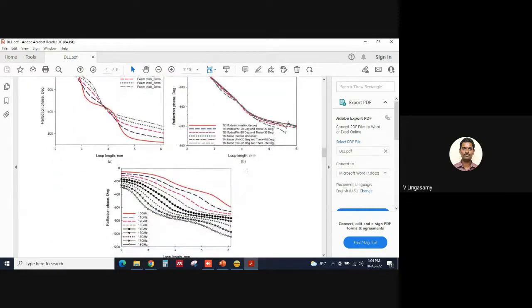This one, the unwrapped phase. These phase curves, right? Unwrapped phase means whenever there is a zero crossing happening, I will subtract 360 so that it gets unwrapped. And then you are getting, for example, plus 500 degrees, minus 600 degrees, something like that, right?